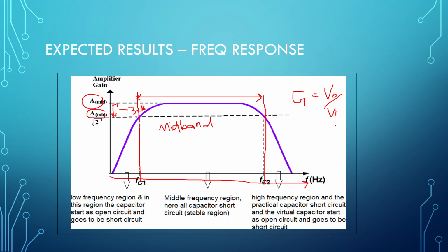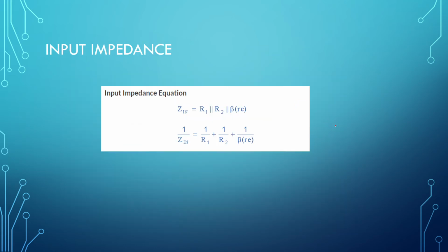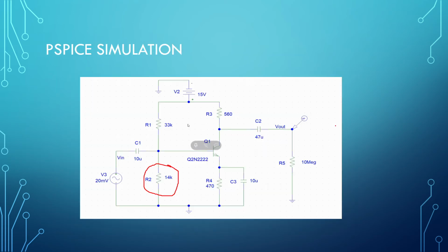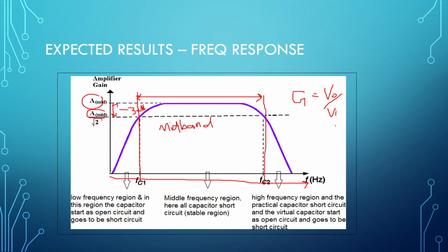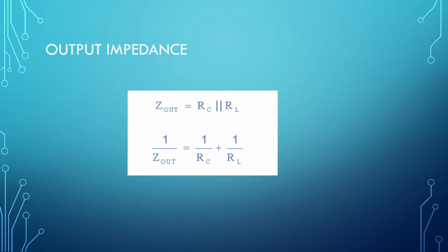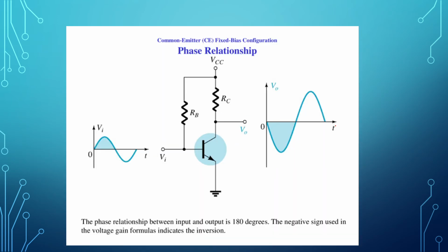And then what you also need to measure is the input impedance. So this is the theoretical value of the input impedance, but for the measurement, it's better if you could show the measured values from the one that I have shown here, the Rin and also the Rout, input impedance and output impedance. This is also the output impedance by theory.